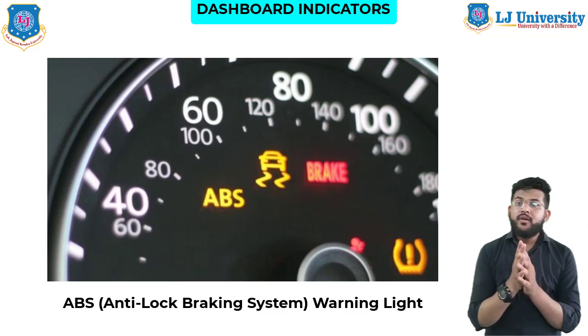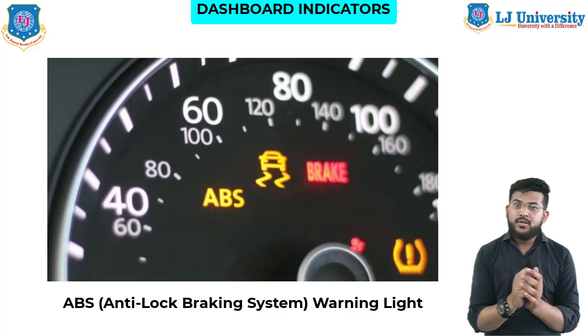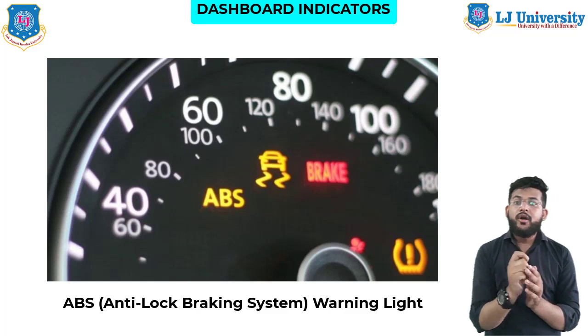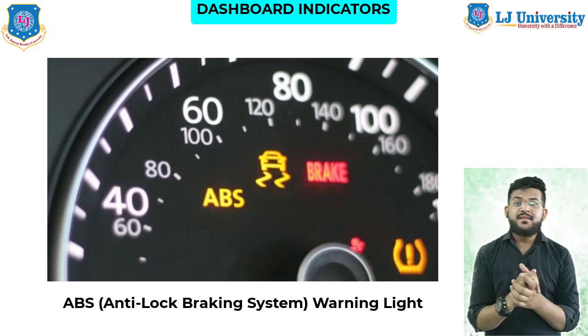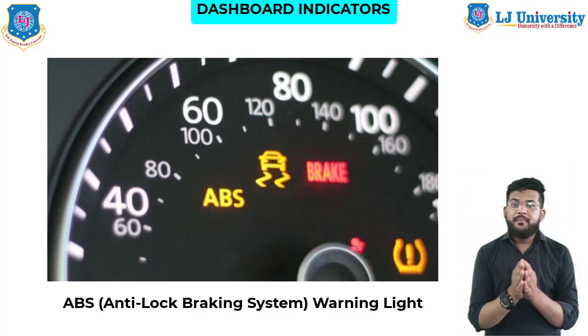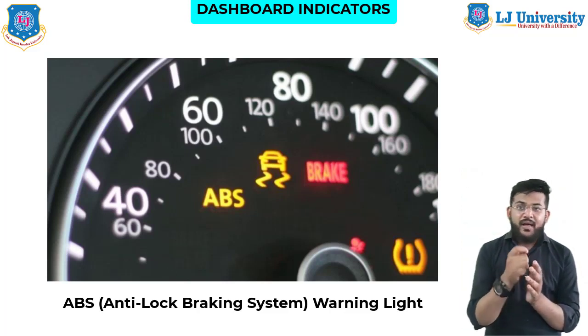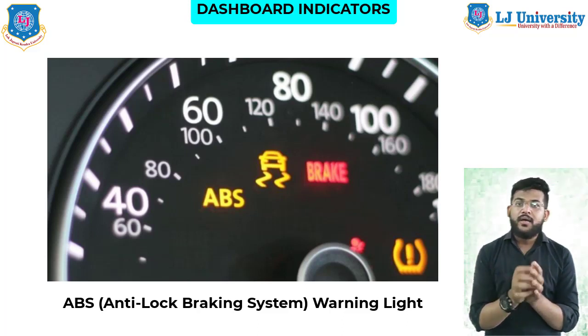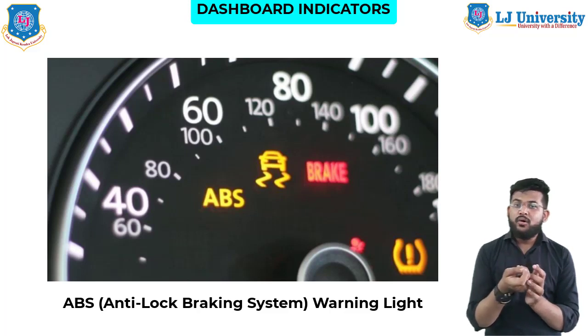A few extremely common reasons for the ABS light to come on include: first, a faulty control unit; second, solenoid malfunction; third, a failing pump; fourth, low fluid; fifth, a bad speed sensor or wiring problem; and sixth, standard bulb checking. The ABS does a test by itself every time we turn the ignition on. So the light briefly comes on, and if the computer system, the ECU of your vehicle, finds any problem, it always stays on.